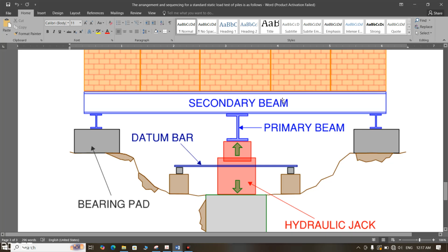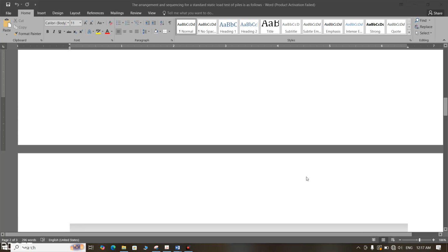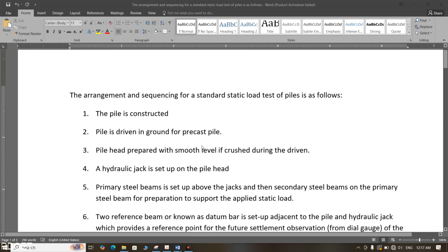During the decremental phase, the dial gauge gives the anticlockwise rebound settlement, and the test is ended after 4 to 12 hours after the decrement. Here I have noted that point.